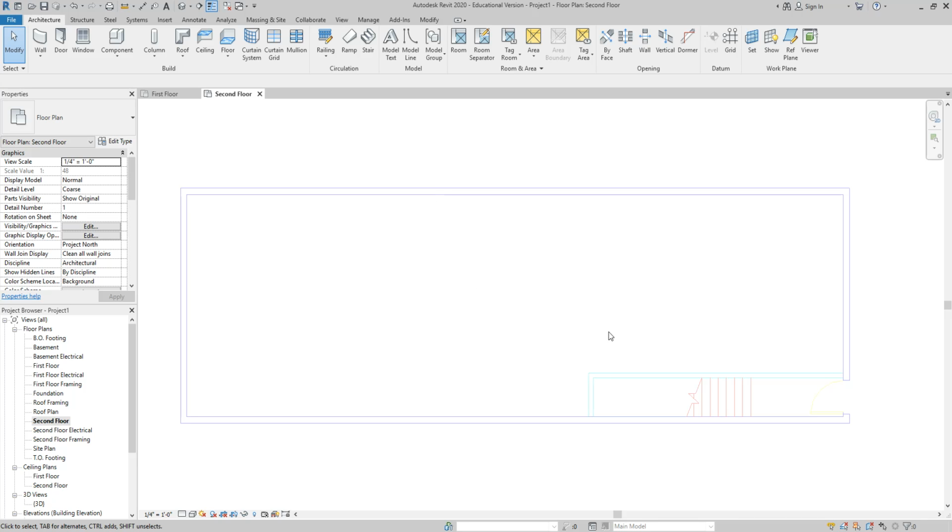Now, is it important for me to have the first floor underlay on right now? Well, I guess to see if it lines up. Yeah, so that we can get the second floor on top. But after that, do I need it? No. So it's good to have it to begin with so that, again, remember in Revit, we're drawing the whole thing. In CAD and hand drafting, you can draw the first floor here and the second floor across the street and nobody will know. But in BIM modeling, they're really going to be stacked on top of each other.